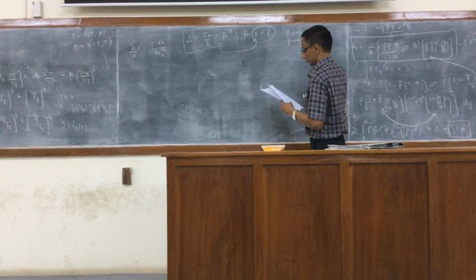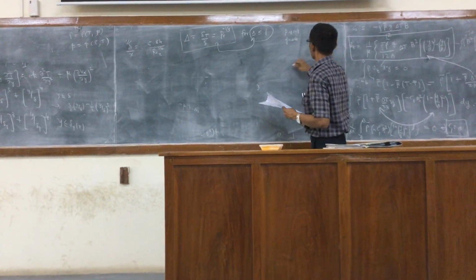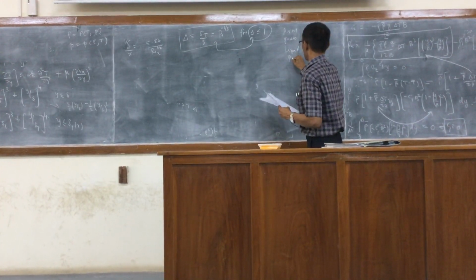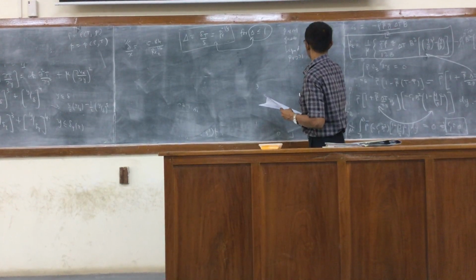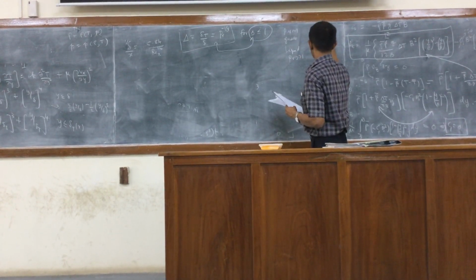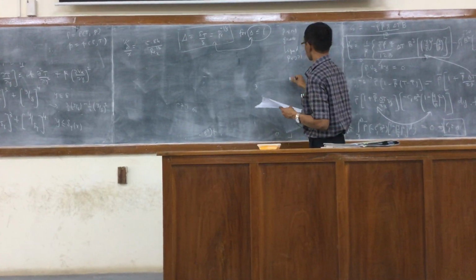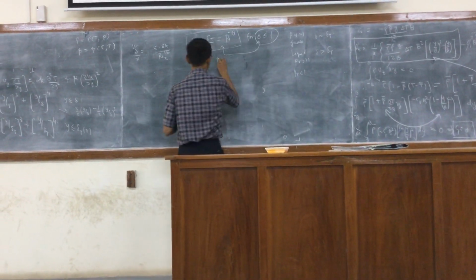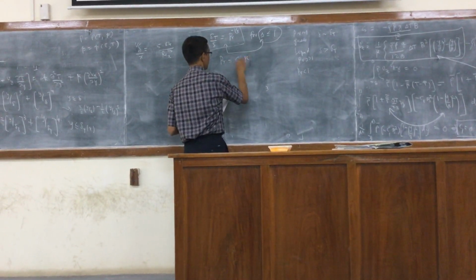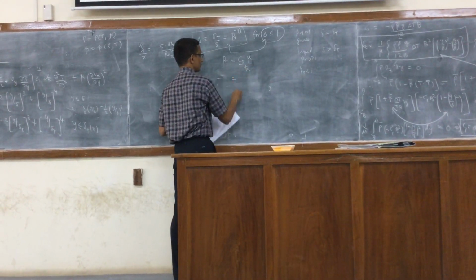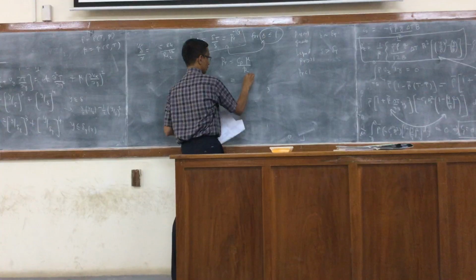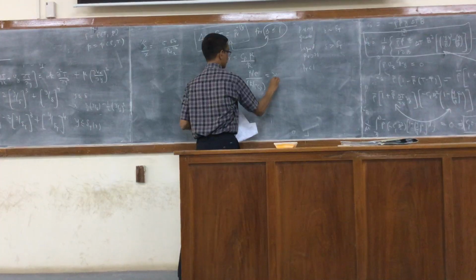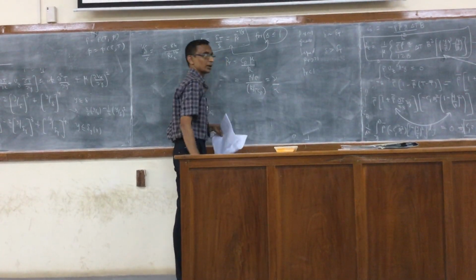Okay, so for gases, you can clearly see that delta will be of the same order. For liquids, where Pr is maybe of the order of 10 or so, you can clearly see that the hydrodynamic boundary layer will be greater. Classic examples are given for Prandtl number less than 1. What is this Prandtl number? It is Cp mu by k, and that can also be written as the ratio of what is often referred to as momentum diffusivity by the thermal diffusivity.